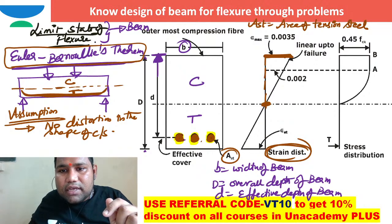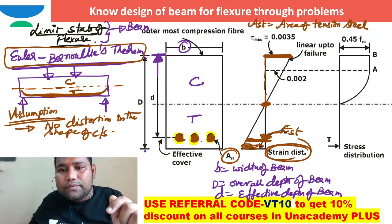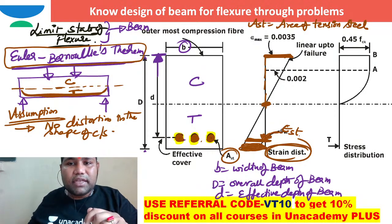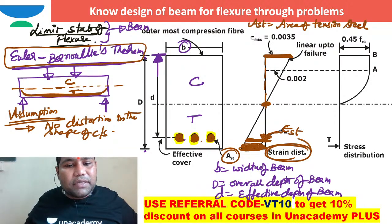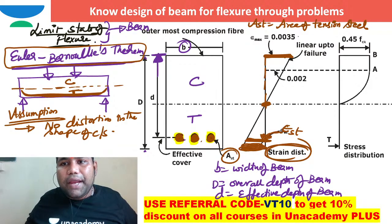And I can say this is the strain in tension steel, epsilon st. The maximum strain is possible at the extreme compression fiber, and at that extreme compression fiber the strain is limited to 0.0035.